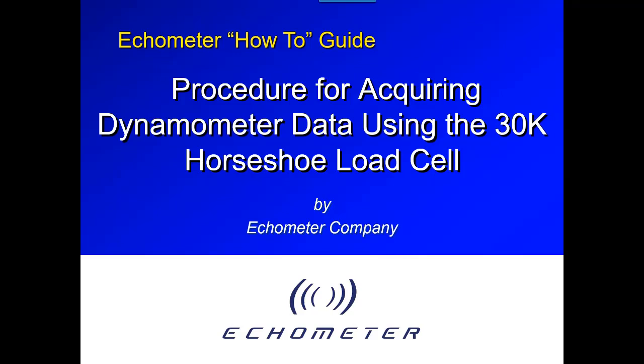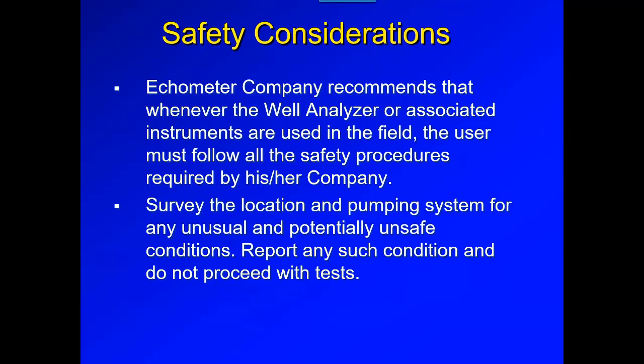Now, one of the things that I want to emphasize is that my stacking out the well in this procedure may be different from what your wells require. There are some stuffing boxes that you can't put the weight of the rod string on. So be sure that however you create the separation between the carrier bar and the rod clamp, you do it in a safe manner that is ultimately recommended by your company. You want to make sure that it follows your company's safety guidelines and protocols.